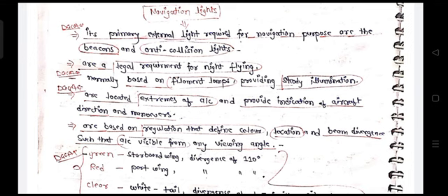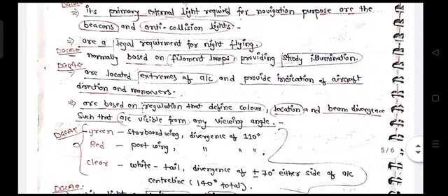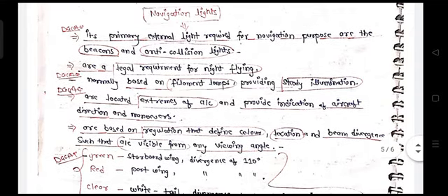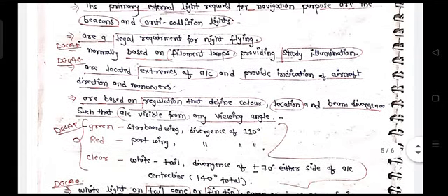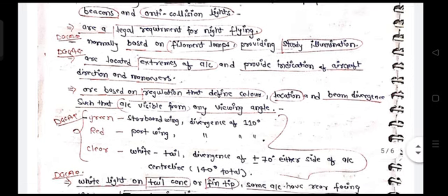Fine. There are also two white strobe lights which flash along with the red and green lights. Also one white light will be there, generally white, at the tail portion. Along with that you have beacons. Beacons are anti-collision or emergency lights. Whenever the engine is on, the beacons are on, and only after the beacon is off should you go to the aircraft. When the beacon is on, you should not stay close to the aircraft. For night flying, beacons are a legal requirement. You have to keep the lights on at night, otherwise no aircraft can find out where you are.